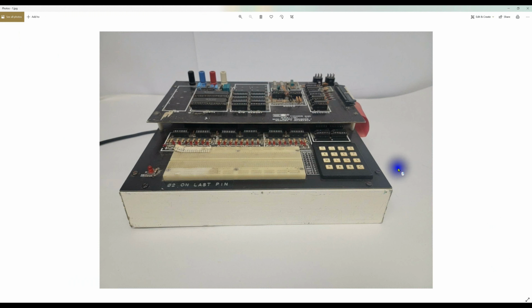This is the one I recently acquired, this unit. I picked it up on eBay. 2 things attracted me to it. It's got the MI card here on it, which is a memory and interface expander. If you noticed on the other one, it was a connector down here, and this runs a ribbon cable up to this board. This board provides additional space for ROMs, additional space for some RAM, a couple of UARTs, and there's a couple of interesting connectors back here that are for a cassette recorder and external RS-232 or 20 milliamp.